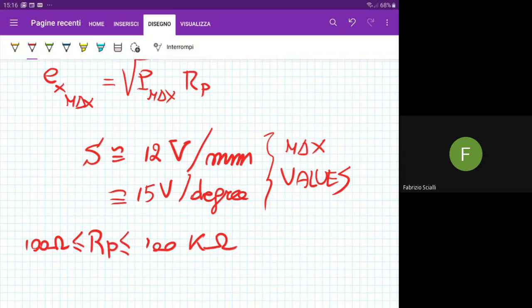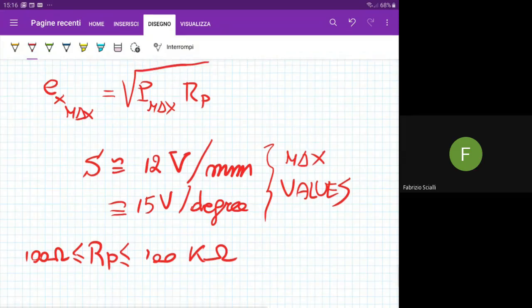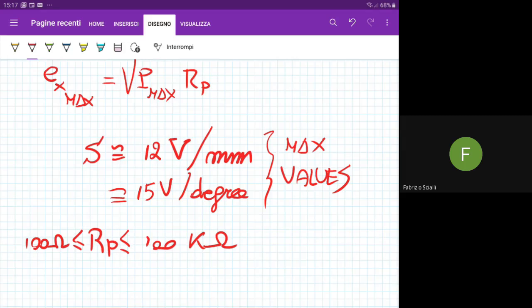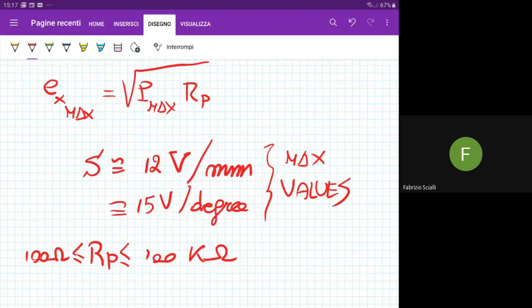So if I have the chance, I can pick the best transducer for my measurement. And just to link this discussion with yesterday's discussion, you have to have a priori knowledge of what your measurement is. If I need to measure millimeters, microns, meters, you know a priori what you're going to measure, and then I can pick my best measuring device.